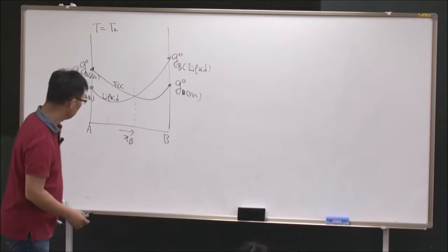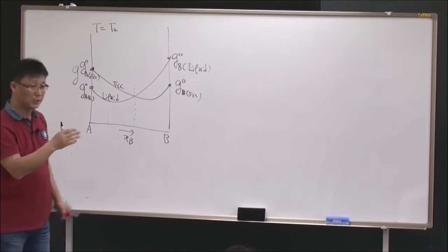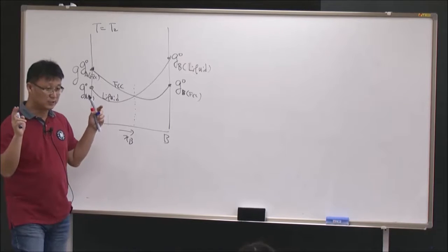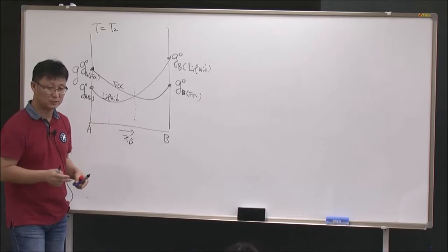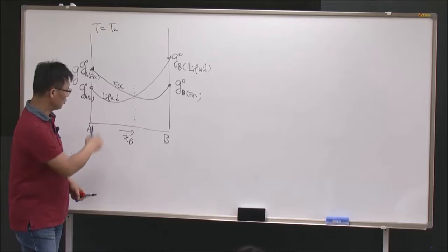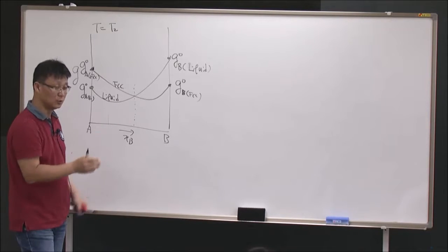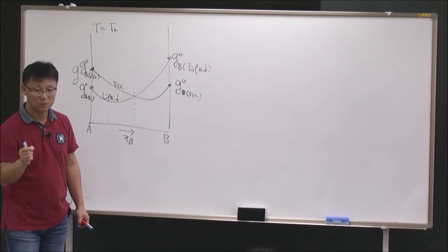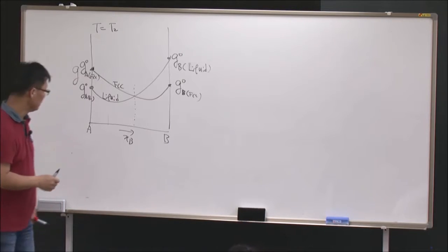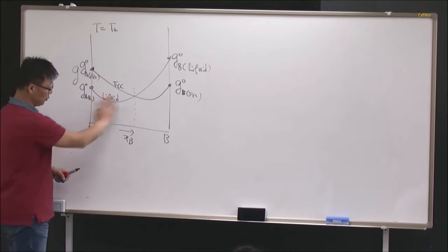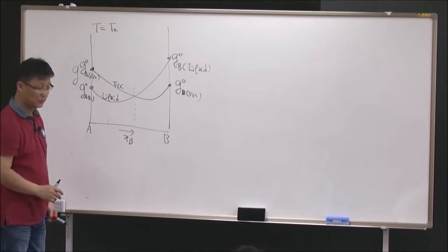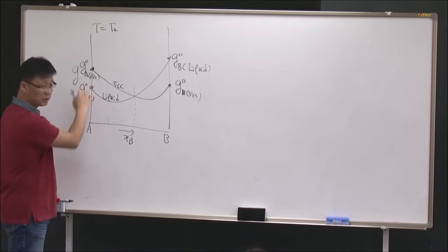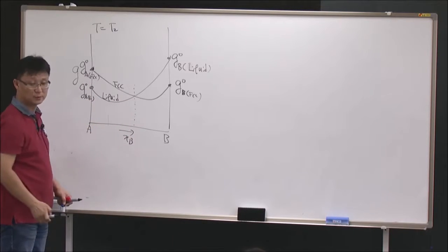Okay? So in order to apply that possibility, that the system can have more than 2 phases existing together, we now have to apply a certain rule, and that is the so-called common tangent law or common tangent rule. Okay? So when we have this kind of Gibbs energy diagram, because we are in 2D here, yeah? At constant temperature, the only thing you are changing from the Gibbs energy point of view is the composition. Okay?